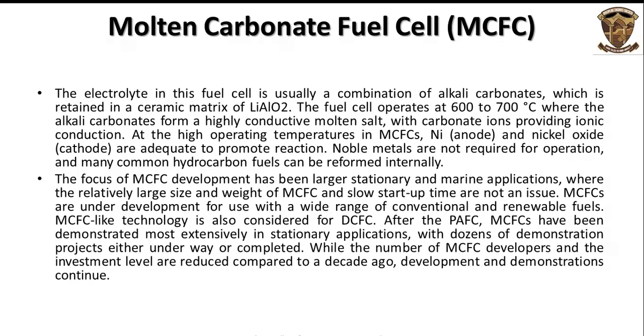At the high operating temperatures in molten carbonate fuel cells, nickel anode and nickel oxide cathode are adequate to promote the reaction. Noble metals are not required for operation, and many common hydrocarbon fuels can be reformed internally. The focus of molten carbonate fuel cell development has been larger, stationary, and marine applications. So, after the phosphoric acid fuel cell, molten carbonate fuel cells have been demonstrated most extensively in stationary applications, with dozens of demonstration projects either underway or completed.